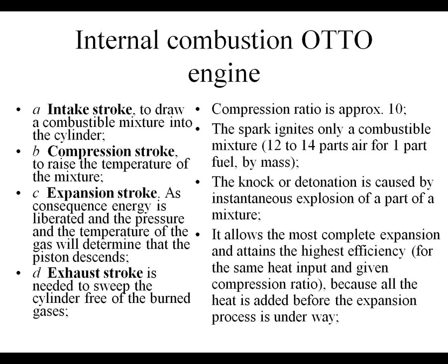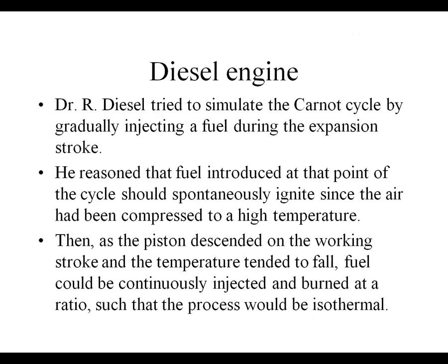So you have to make the difference between the Otto and the diesel engine, because for the Otto you must avoid very high temperature, meaning the compression ratio is limited, and the compression ratio for the diesel engine is much higher, because you have to reach a high temperature for the self-ignition of the fuel. The idea of Diesel was to create a Carnot cycle, but it is not possible to create it. But he tried, and the result was successful.